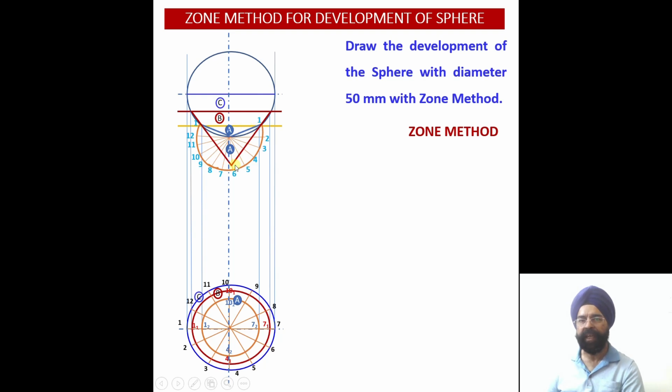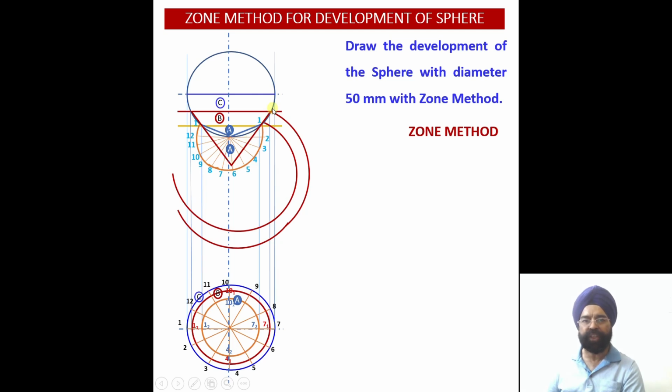This cone has been assumed to be cut over there. So this portion we are going to assume has been removed, and this was the original cone, right? So now this is our slant edge for the uncut cone. So what I am going to do, please check from here. I'll open compass equal to this much. Again I repeat, I am going to open compass this much, and once I open compass equal to this radius